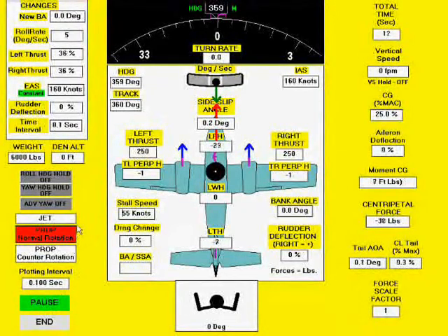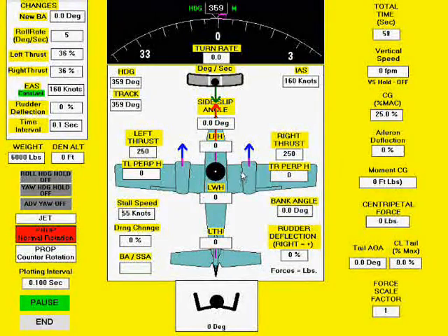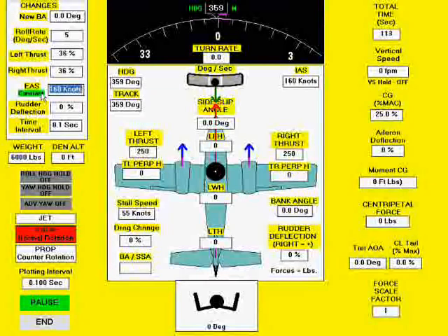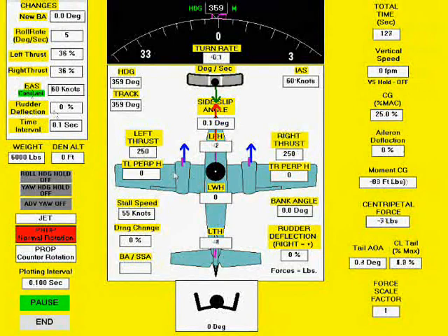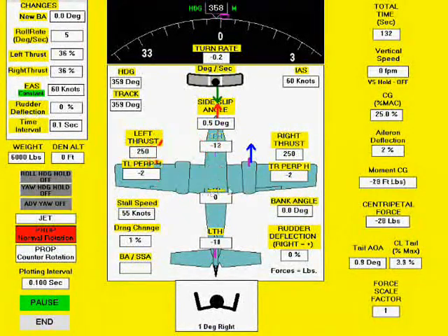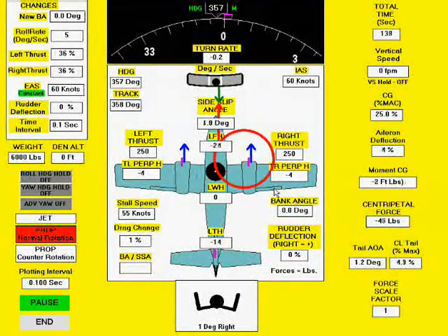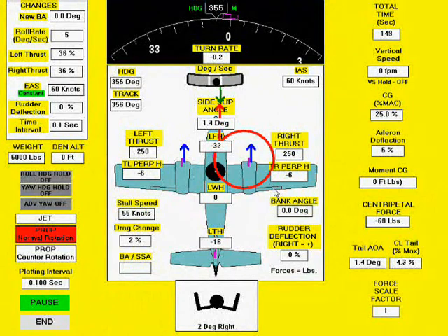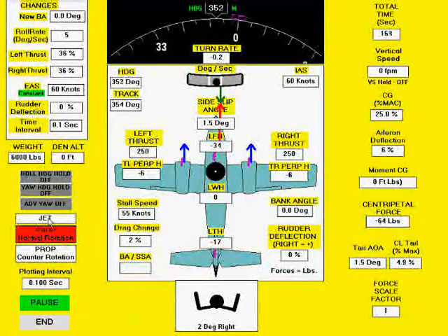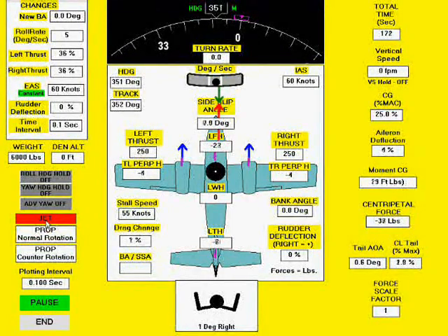On the lower left of the Yaw Axis Simulator, we see three boxes that can select the engine orientation. For normal rotation, viewed clockwise from the cockpit, we see very little thrust shift at high speeds. If we now slow to a slower speed, we see a pronounced shift in the thrust vectors to the right. This makes the moment arm of the right engine larger, which produces a stronger yawing moment if the left engine were to fail. Therefore, the left engine is the critical engine. If these were jet engines, there would be no shift in the thrust vectors, and therefore no critical engine.